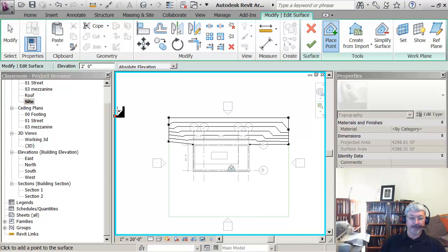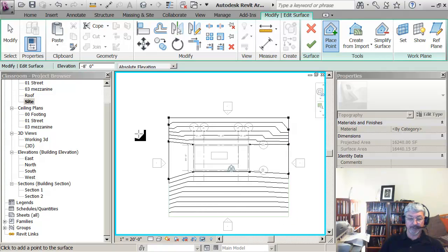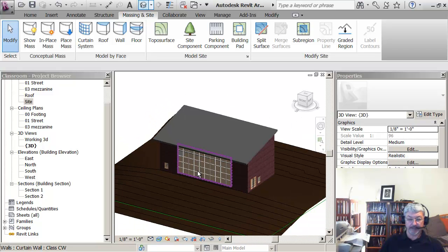At the front of my building, I'm going to drop it a little bit. Suppose I'm going to expose some of the footing so you can see it, so I'm going to pick 1 foot here and here. I'm assuming there's a general slope to the south, and then let's drop it quite a bit, maybe minus 8 feet at the front there. So that's actually my terrain model. Again, I need to say finish the surface, and I can look at it here and see the terrain.